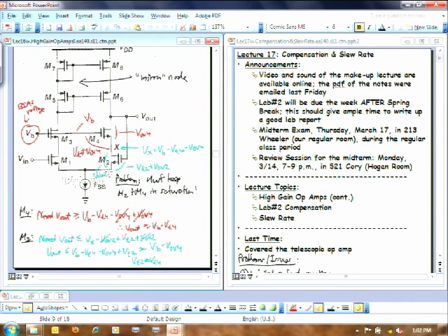And you had a question. Yeah, if you change from VDD, what if you use... Oh yeah, if you increase VDD, you can increase your output swing. Yeah, for all of those things you can increase output swing. However, no, okay, you're right. In unity gain you can't. In unity gain it's always going to be that, because that's constrained not by VDD, but by what's happening in here between these. So you're going to have a problem with the unity gain right there. But in general, when you raise VDD, that helps you.